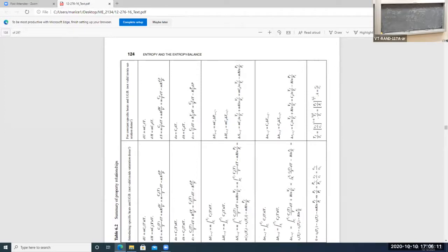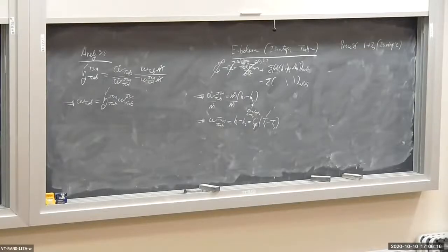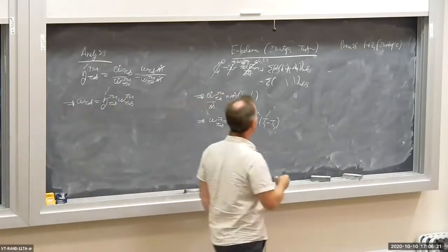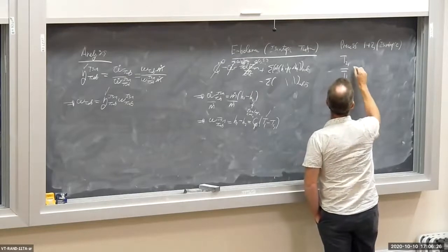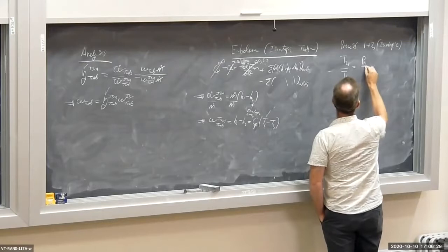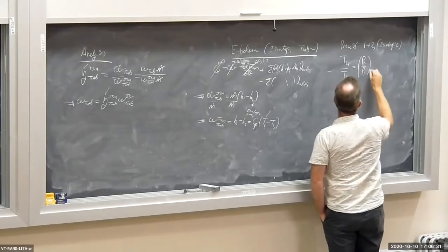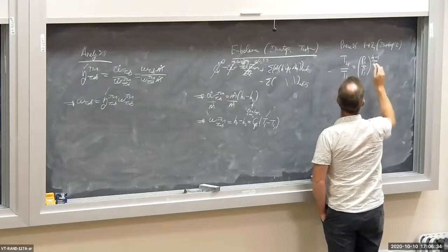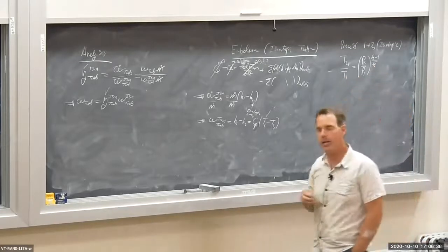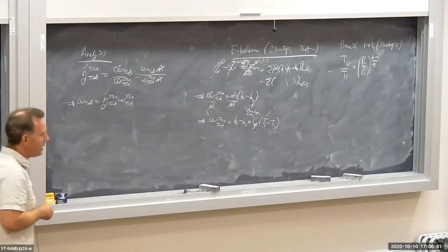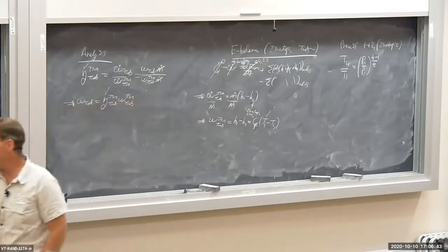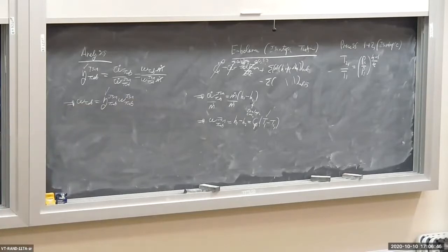Let's use this to calculate T2 sub S. T2 sub S over T1 is equal to P2 over P1, K minus 1 over K. And that's from the constant specific heat isentropic property relationship. To do this, I need K, the ratio of Cp over Cv. So I guess I need to look up some specific heats here.